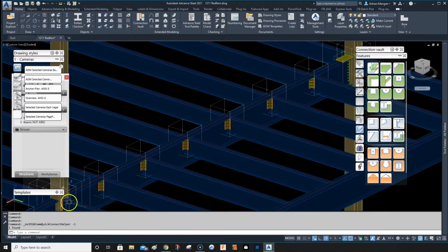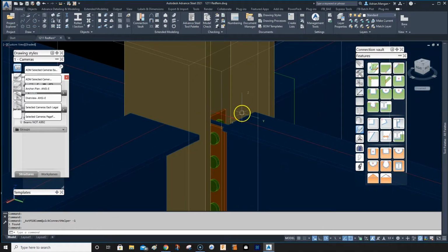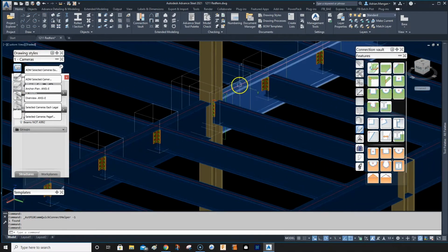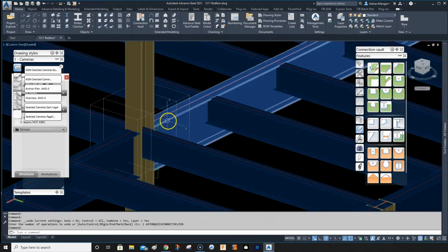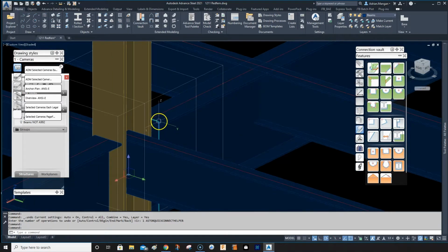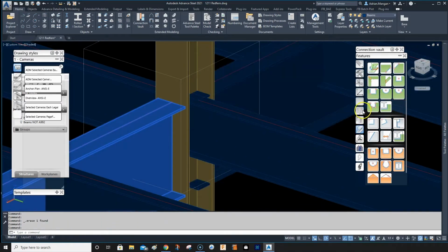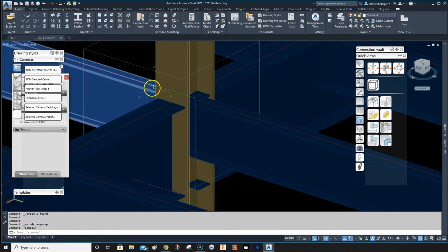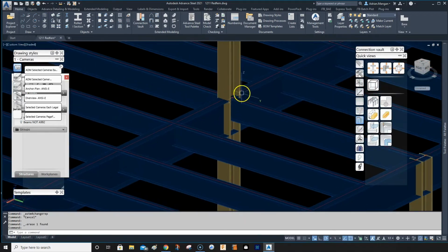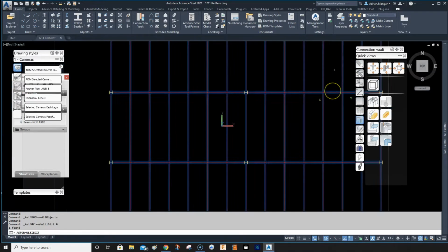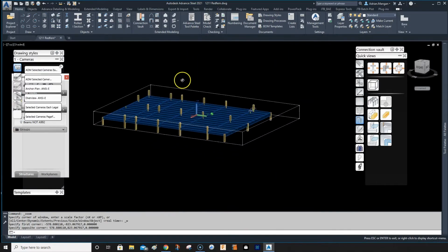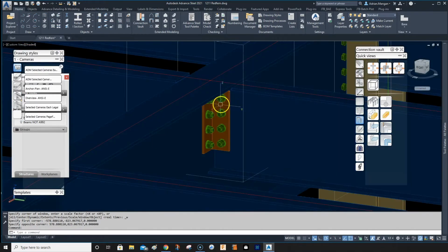As we can see down here, it has propagated this, and it still has propagated back to these beams. So for now, I don't want these cuts here, so let's delete this. Select this one, change the visibility, and delete that feature also. Let's turn everything back on, click on this model view, and let's come in here. Let's check this joint first.